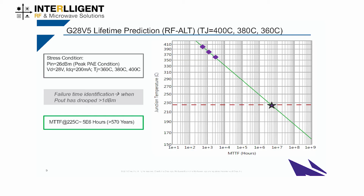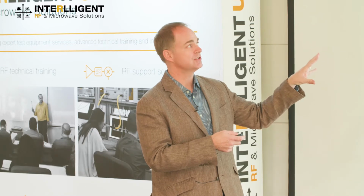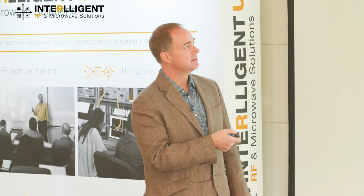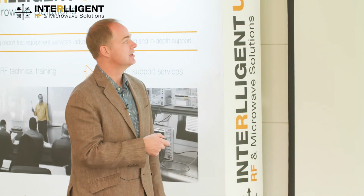And then, as I mentioned, also reliability. One of the key drivers and key aspects of gallium nitride is the ability to operate at higher junction temperatures. So we typically spec our junction temperature limits at 225 degrees C. You can see for our V5 process, we've completed Arrhenius testing that projects out to 5e6 hours at a 225 degrees C junction temperature. And this was all done under RF ALT. So this is actually RF driven temperatures, with the testing done at actual junction temperatures ranging from 360 to 400 degrees C.